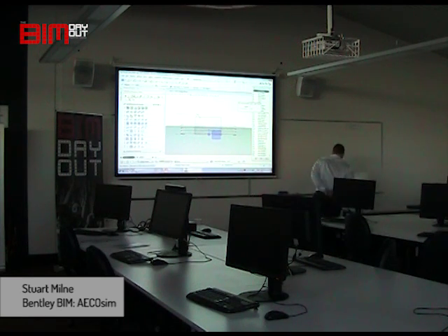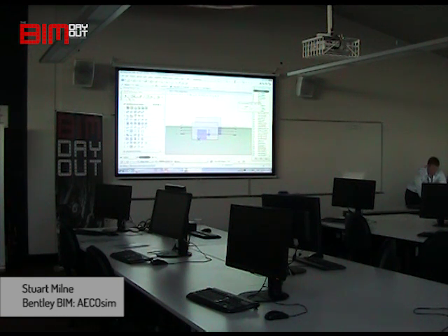Do you want me to show you again? Let me show you again, very quickly. And remember, right mouse key cancels any operation. So if you grab something, just click the right mouse key. We click on any of them, just somewhere along the lower portion here, like that. And if you've got the wrong object, in this case I've got the right one, you just click the right mouse key once, and it will siphon through any overlapping elements.